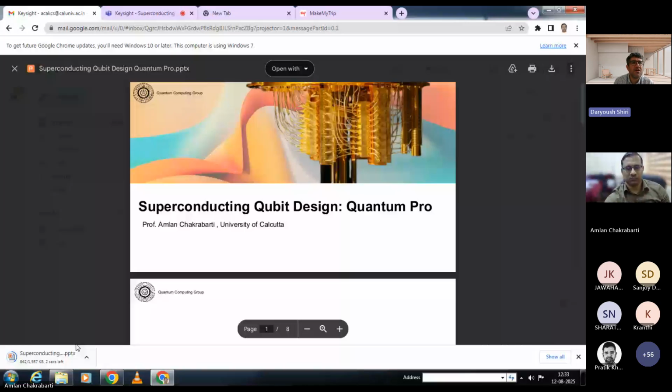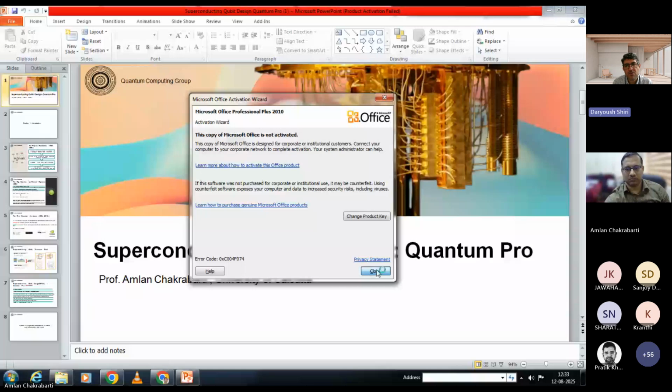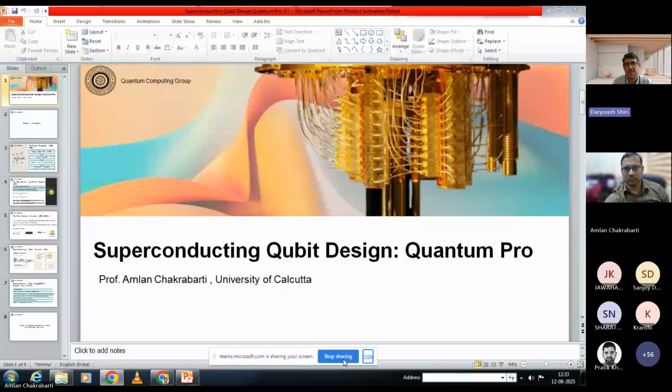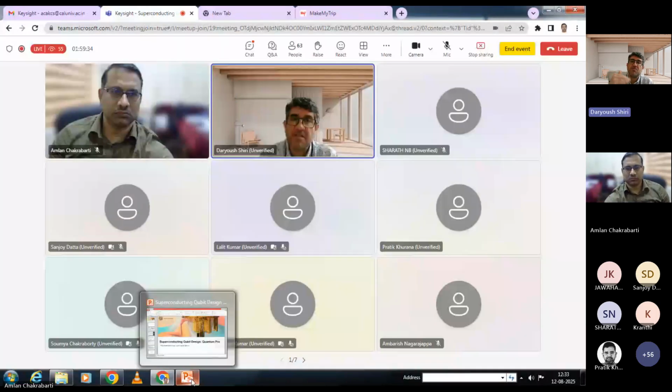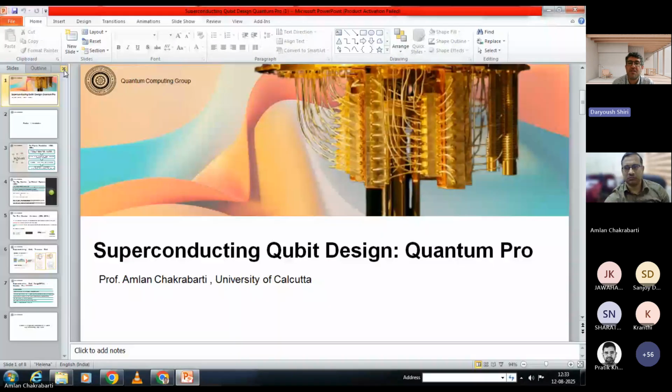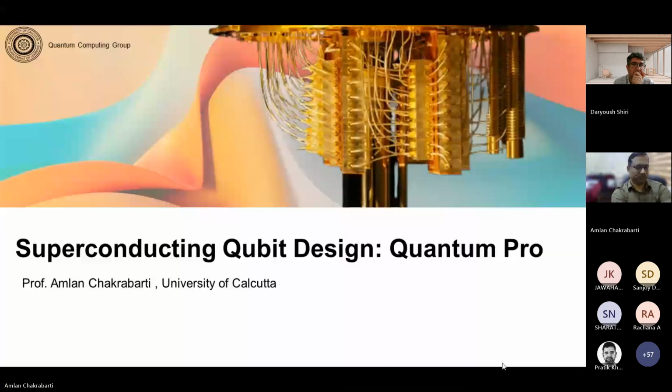You will see conductor air bridge. Just click on that, and then just draw here. Since the thickness in the technology file is already defined, how high it is. In the default setting, it says that this is 8 micrometer high. So it's like a bridge, bridging over this purple thing by 8 micrometer. I hope.